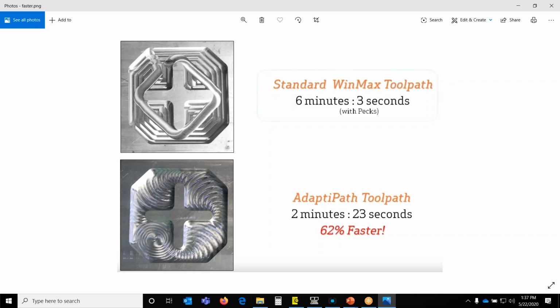Luke had another good comment here on one of the application engineers. He works for one of our distributors. He was saying his engineer was able to push a tool at 350 inches a minute on a VM10 using a coated end mill in 4140. It was using AdaptiPath and cut dry. We see this a lot.